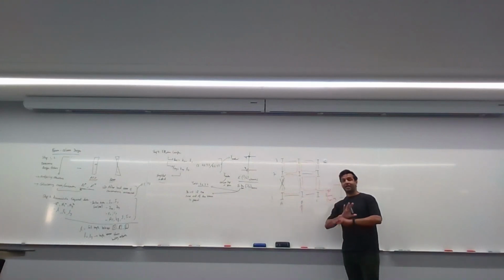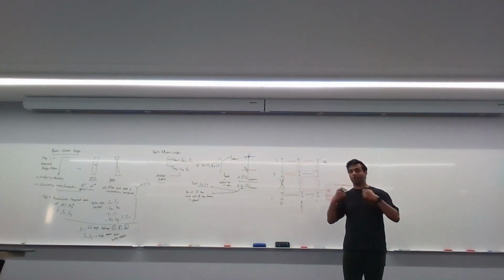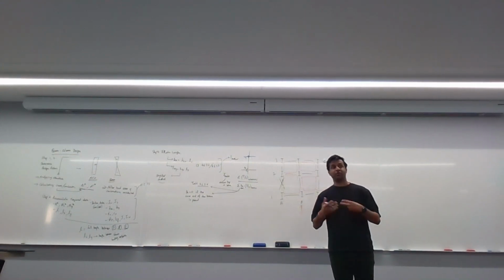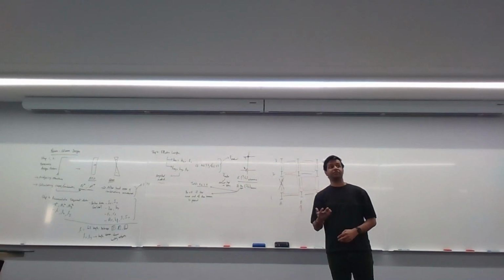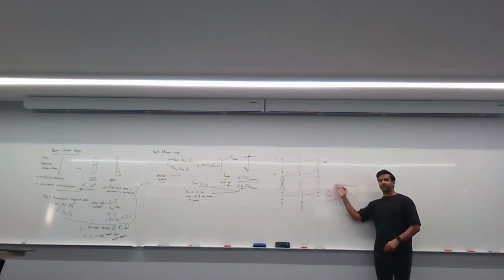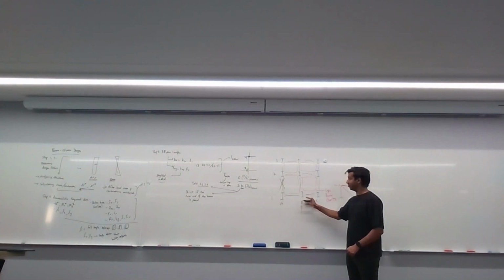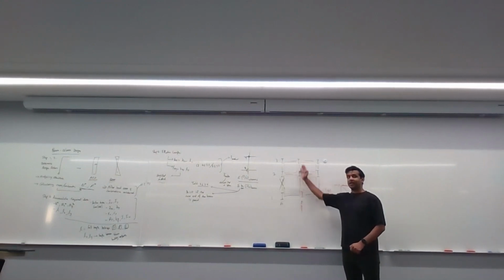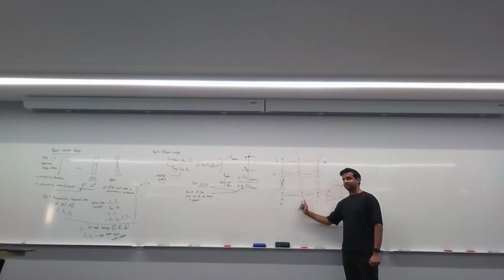But remember what I came back to earlier: whenever the code asks, or the question asks, or you ask yourself, is a frame braced or sway? The question is, is it braced against movement across the page? So for example, if I'm talking about frame B, which is this frame, I'm really referring to forces like this.